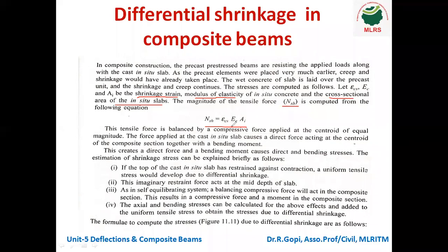It is shrinkage strain multiplied by Young's modulus of concrete multiplied by the area of the in situ slab. So if you multiply all those things, we can get the tensile force. This tensile force is balanced by a compressive force of equal magnitude applied at the centroid.